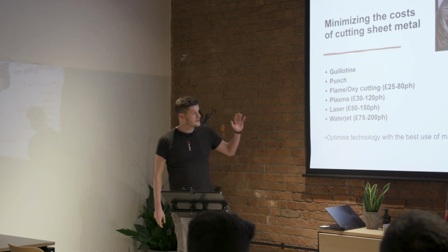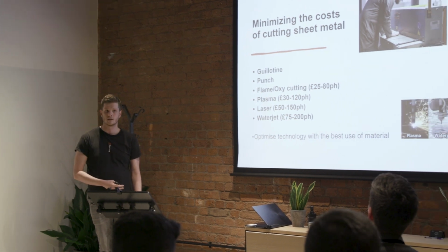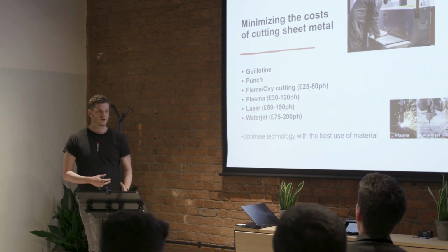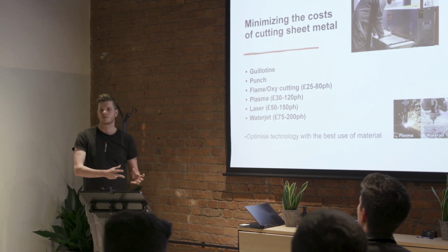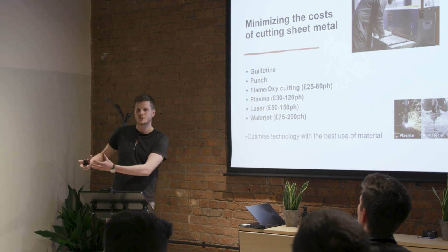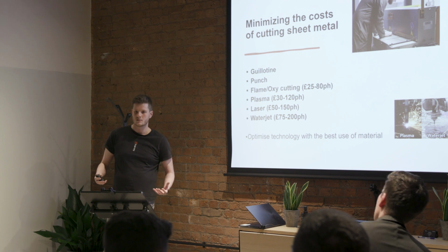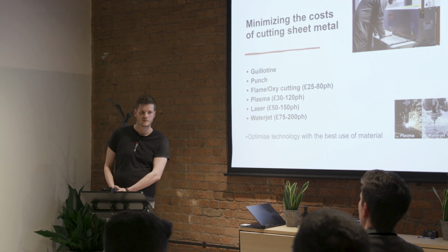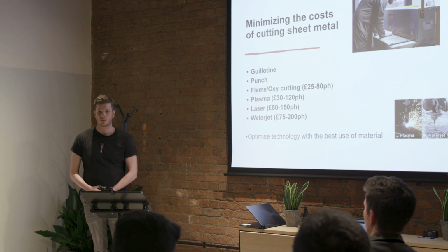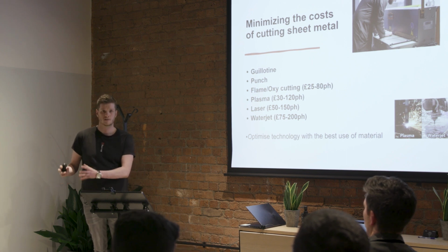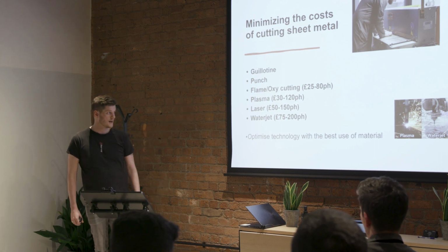Interestingly, quite a lot of jobs that I see come through in laser could probably be switched down to plasma, just because they could probably accept a little bit of a lack in cut quality, particularly for parts which might not be customer facing. So internal components which are just that little bit thicker, or if you work in an industry such as the sewage industry, for instance, where you don't necessarily care too much about how those cuts look, you just want a piece of metal cut to fit a purpose, then you might as well cut down and save yourself some money there.